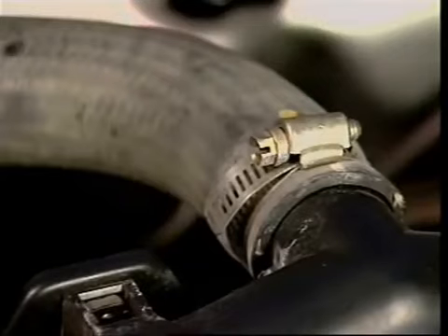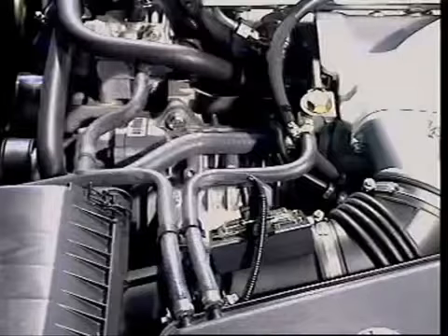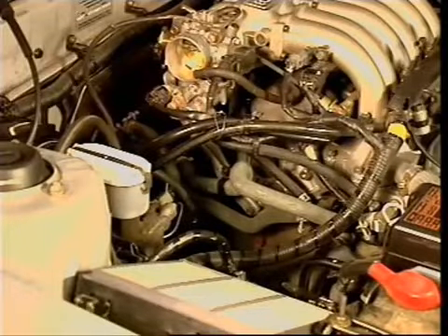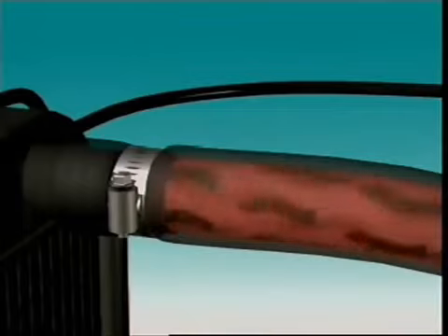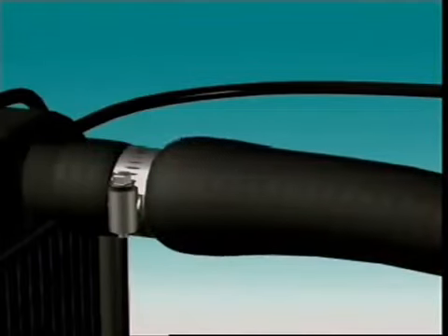Most hoses are made of rubber, and since they are subject to pressure, they are reinforced with a layer of fabric. They are moulded to a special shape to suit the model and make of vehicle. Some heater coolant hoses also have special shapes. All hoses are subject to hot coolant and high underbonnet temperatures, and they can deteriorate and fail.